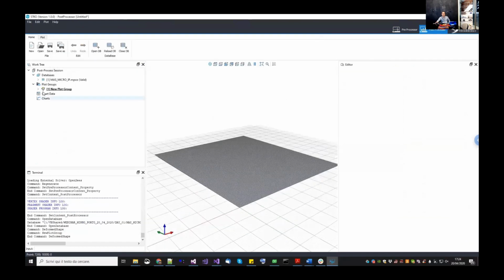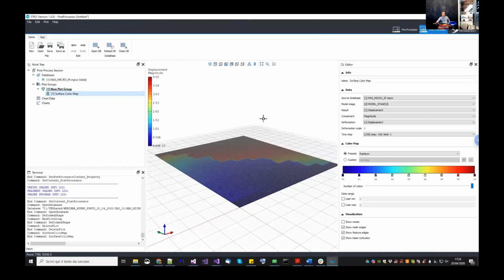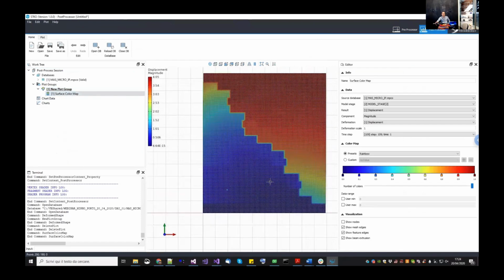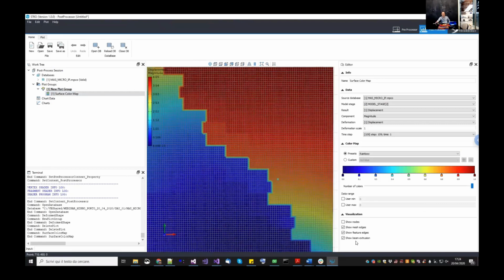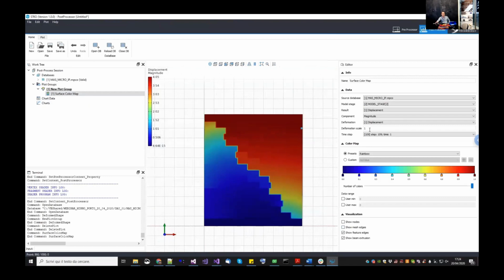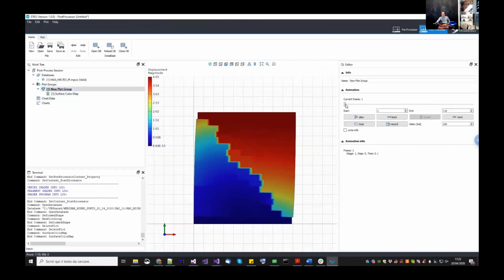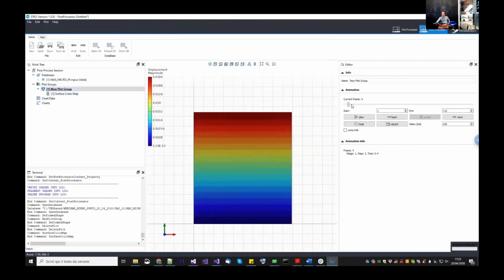Micro in plane. Okay. So here it has a quite fine mesh, but actually you can obtain very good results even with a coarser mesh. Let me show you a little bit what's going on here. So this is in terms of displacement, what we're going to obtain. So we first apply a vertical load, then we apply a constraint keeping the vertical displacement fixed of this wall. This wall is actually the Rainmaker wall tested at Eindhoven. I will send you also a reference for the material parameters and everything for this.